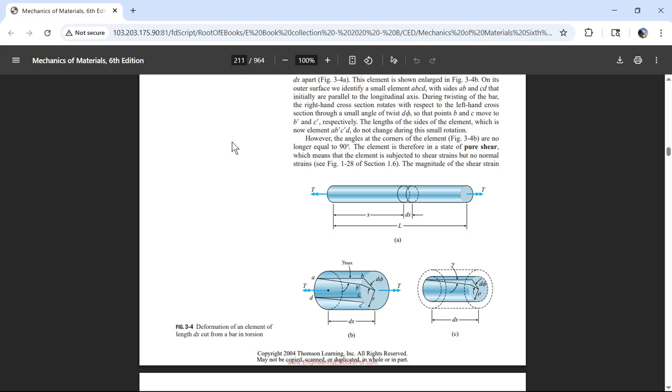But that's why I think, from a jobs perspective of trying to keep people safe, keep your job safe, keep everyone safe, keep your tools unbent. Think of bonds as being covalent, where the second you bent something, well, hell yeah, you did something wrong. You probably killed something. If you think of material mechanics like that, then with yield, wild things happen, and you can actually design for parts of things to yield and others to take up the slack. But if your climbing carabiner starts to yield, you got issues.